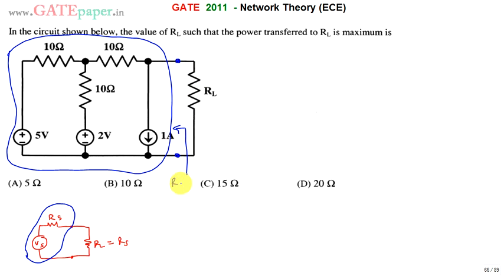So if you get some equivalent resistance, we can say it is equal to Rs of this circuit. If you are able to find the equivalent resistance of the complex network looking into the load terminals, then that value is taken as the load resistance. Then maximum power can be transferred from that circuit to RL. How do you calculate this R equivalent?